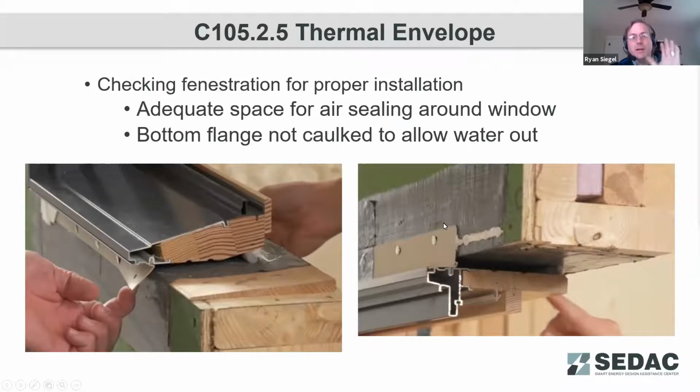So it's only trying to keep water out, which it's much easier to do when you have the same pressure on both sides of your seal. Whereas the inner seal provides that air seal, that allows your air barrier to be continuous, and that inner seal avoids UV and most of the weather degradation. So that allows that inner seal to remain in much better condition over the life of that building.